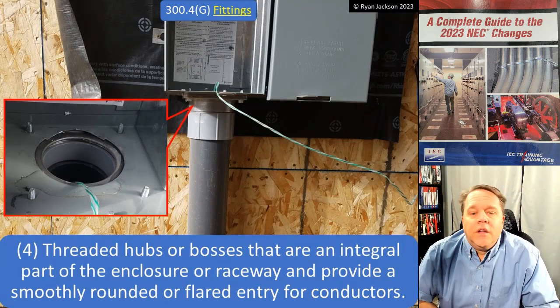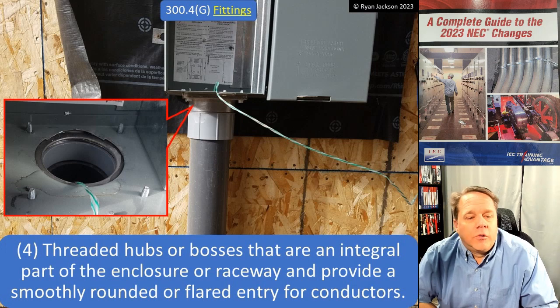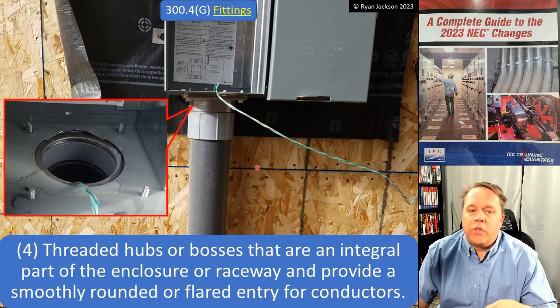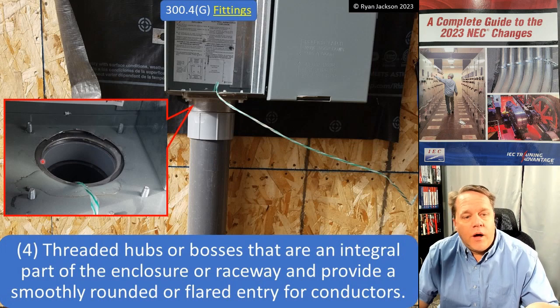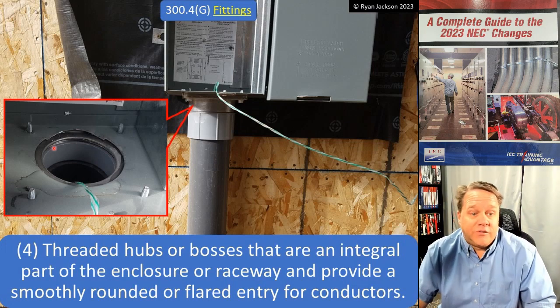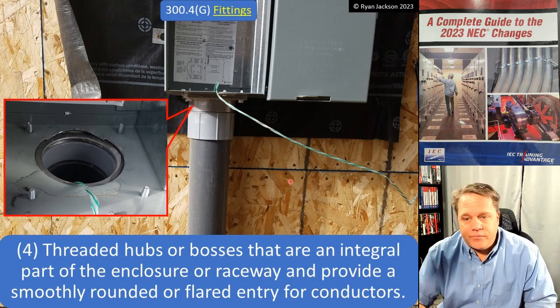Option 4. Threaded hubs or bosses that are an integral part of the enclosure or raceway and provide a smoothly rounded or flared entry for the conductors. All right, so here we've got our hub on the bottom. We thread our conduit into it, smoothly rounded, good to go. That would be another option. Certainly you're not going to put a plastic bushing on that.